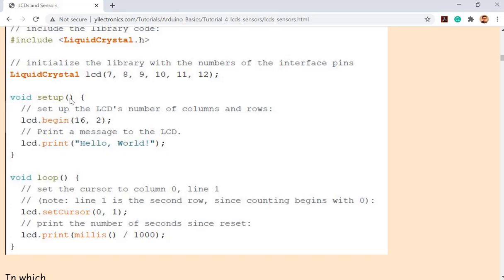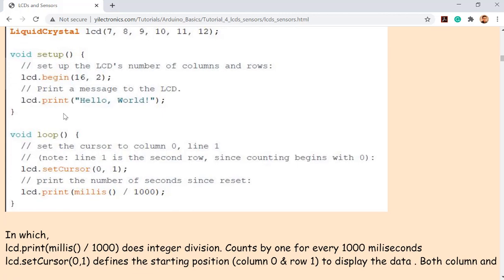And for the setup function, will be executed for how many times? How many functions do you have in any sketch? Normally, is that 2? The setup function and the loop function, right? The setup function will be executed only once whenever you power up the microcontroller, and the loop function will run forever. After the setup function is done, it's going to start the loop function and keep going back and forth inside the loop function.